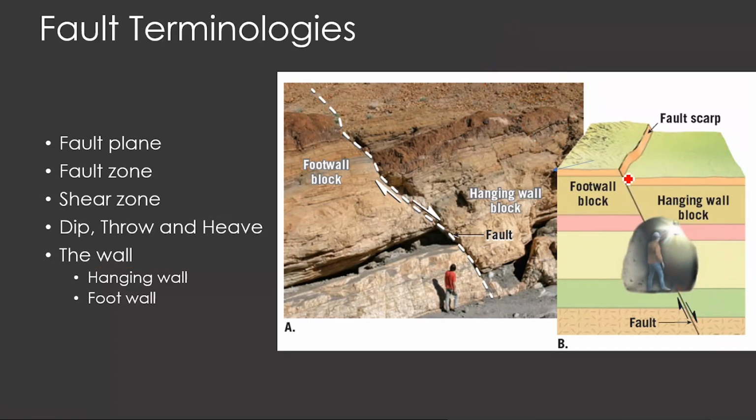So here in this case, which is the fault plane? This is the fault plane, a three-dimensional fault plane. And which block is above the fault plane? You have to imagine that you are keeping a slanting plane, and the block is above it in this direction. I am not talking about the left side block being slightly above if you are taking the vertical displacement. I'm talking about this block which is placed above this plane. So this block is called the hanging wall.